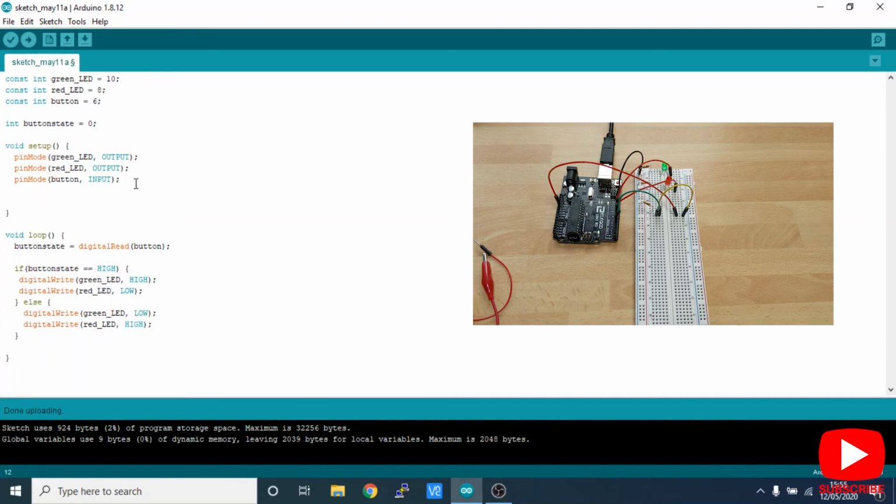First thing we need to do is in our void setup, we can go Serial.begin. So that's going to open up our serial port, tell it that we want that serial data. If we don't do that, there's no data being shared between the Arduino and the computer other than uploading the new sketch. So you need to tell it you want it open. And you need to set what's called a baud rate, which is basically the rate at which information is being sent. The standard is 9600, but there are more options, but for now we'll just say 9600.